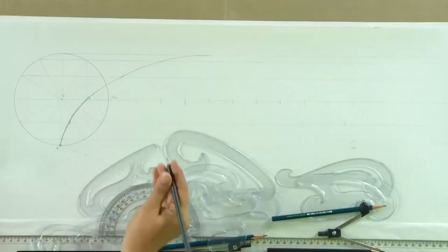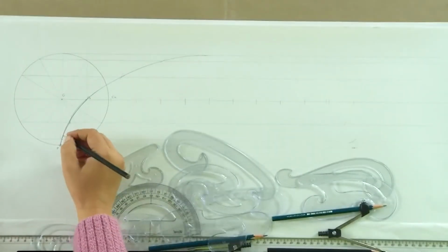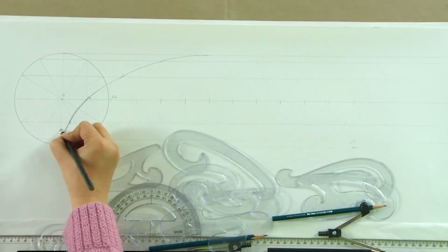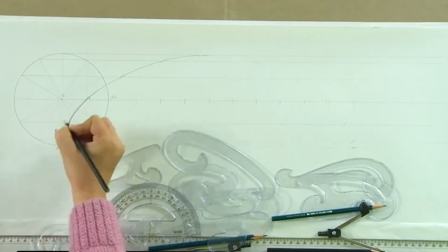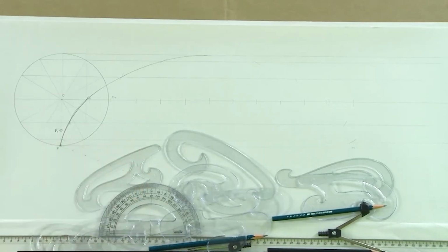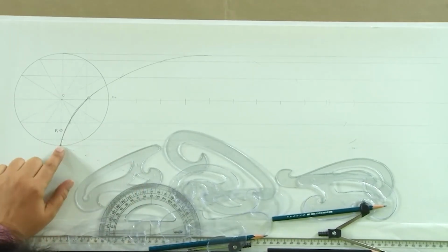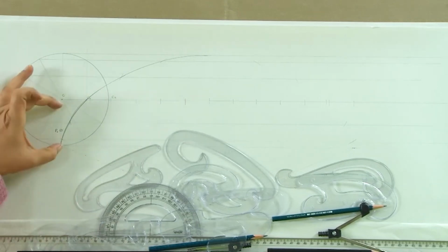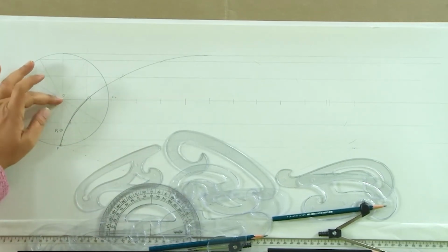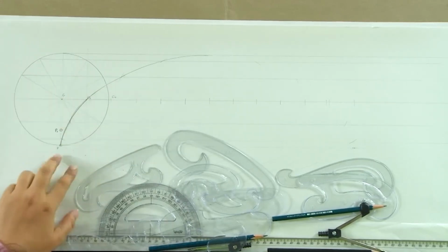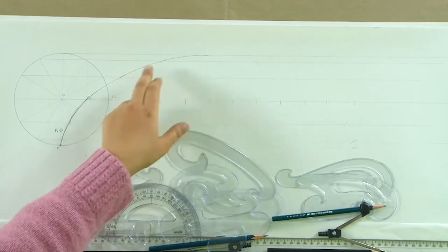So, if we were to draw a trochoid, the only thing we would do is, for example, we had a point which was not this, but there was a point P1 here. So, instead of this point and the distance CP, we would have taken the distance CP1 and we would mark the movements along these horizontal lines.